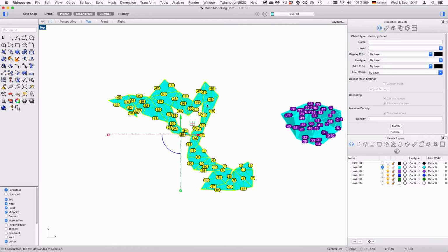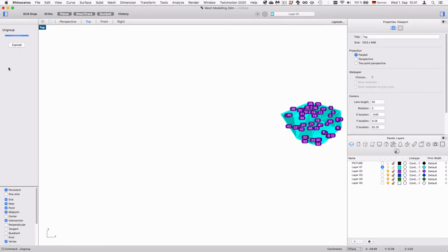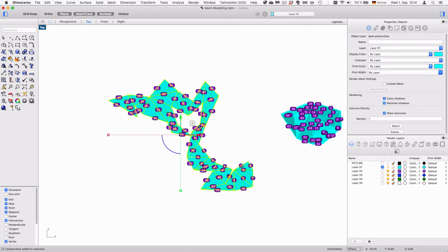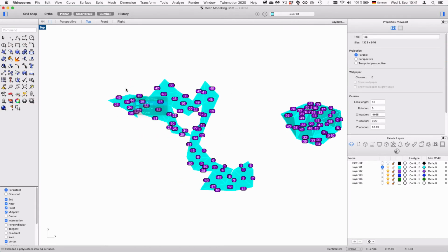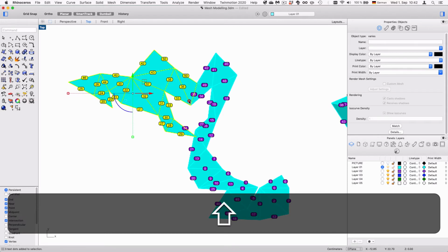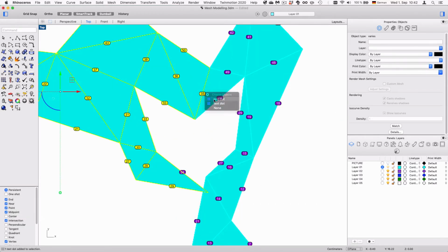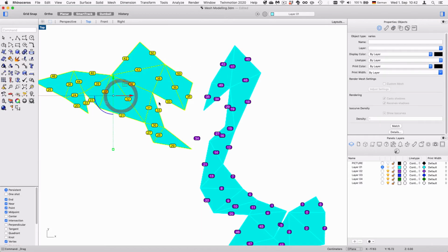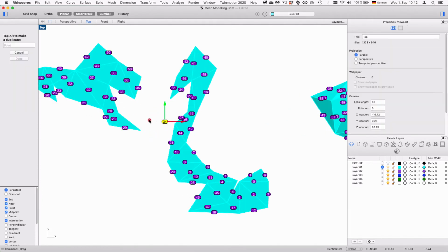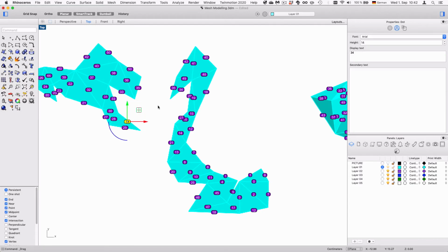And yeah, what you want to do now is ungroup that, and you also want to explode this one here, so you can really work with it. And again, turn off the ISO curves. Now you can select all the single surfaces. What you can do, for instance, is take it apart, because you have to print it, let's say. You want to move it apart and put that onto a different sheet of paper. And maybe same goes for another place. Oops, here we should move the 34 over here.